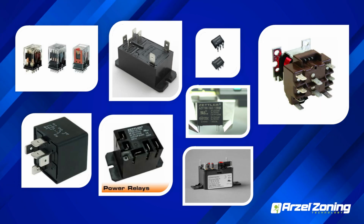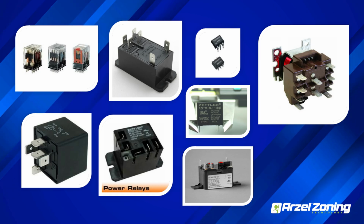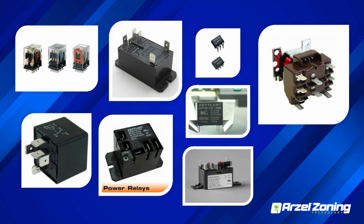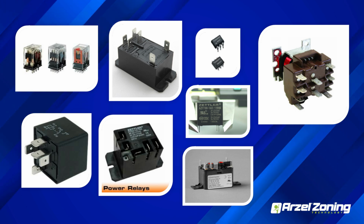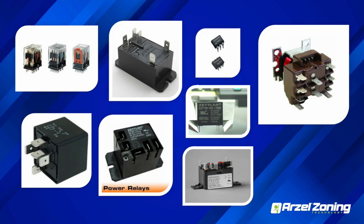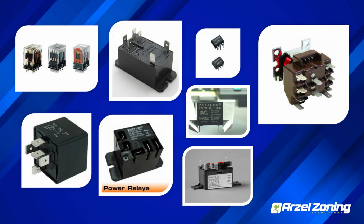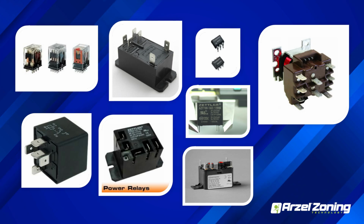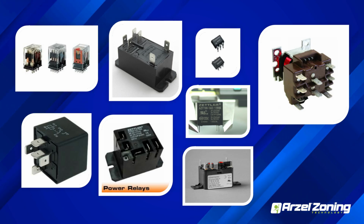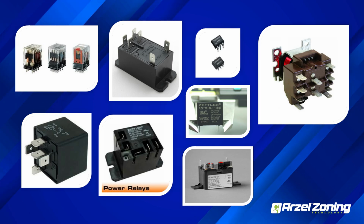They take many different shapes and forms. Some of the ones on here were more common in the HVAC industry, so we're a lot more familiar with them. That one in the lower right corner, that's very common for truck stock to have one of those for humidifiers. The brown one there on the right side, it's not quite as popular today, but a fan center relay for a boiler system or a really old furnace that didn't have the control boards that we have today. It was a relay that plugged into the fan center socket, and that's what gave us our control of the HVAC equipment. So relays are in every part of our industry, and they really haven't changed as far as operation goes. They've just changed in appearance.